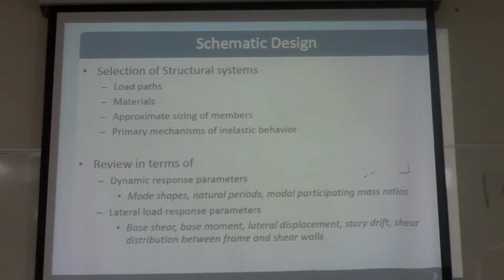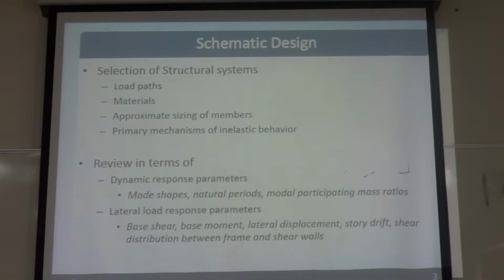And we have to calculate the probable shear demand due to the moment capacity and design the beam that should not fail in shear, but we allow the yielding in flexure. So the beam moment demand will exceed the moment capacity, but shear demand should not exceed the shear capacity. Those kinds of things we have to consider in the inelastic mechanisms.